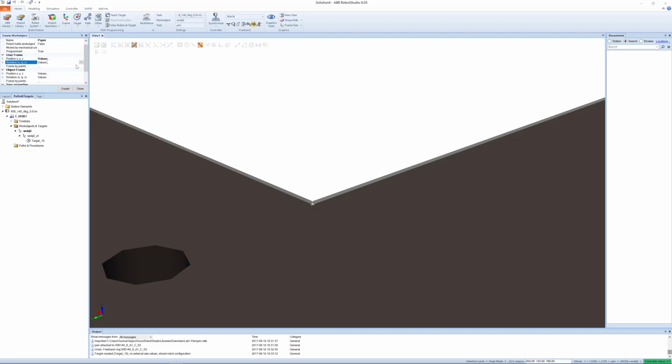We have some values for the rotation. We want the Z-axis to point downwards, which will be the same as the tool center point of the pen on the robot when it is writing. So we have to reorient around the X-axis 180 degrees, except that one.